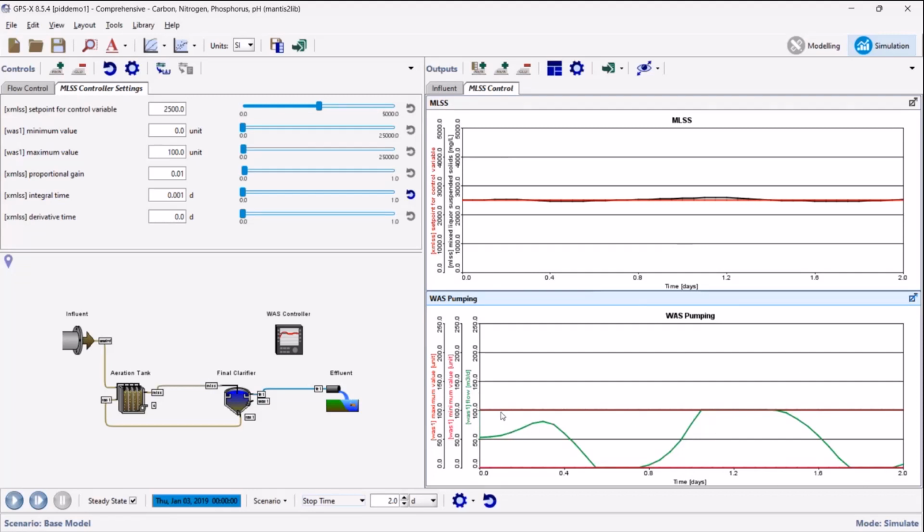This is also a good point to see here that the controller came up here aggressively and then it hit that max, right? So you can see that it can't really do the job that it wanted to do up here. Eventually it came down when the loading changed anyway. But just to point out that if you see this kind of fluctuating up and down behavior on your manipulated variable, then that means that probably your controller is not quite where you want it to be, even though it's actually meeting the set point.